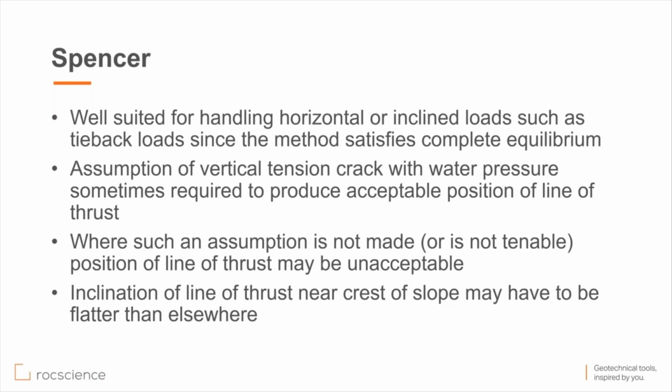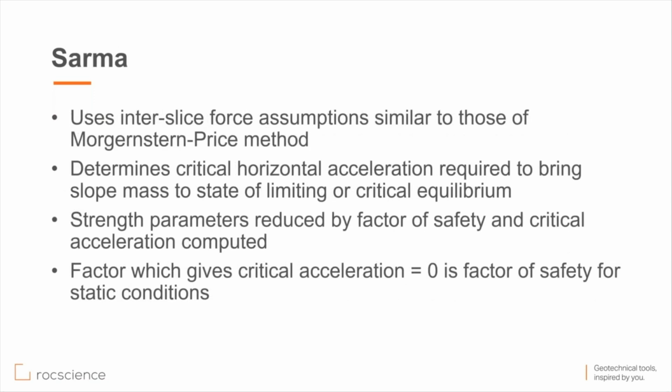Very important. And when you look at your line of thrust and you are struggling with it, you don't like it, it seems to be problematic, you may have to include tension cracks in order to resolve the problem. But we will look at that a little more in our discussion. We'll talk about that again.